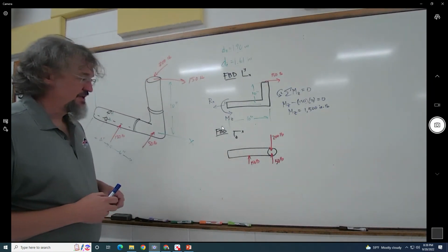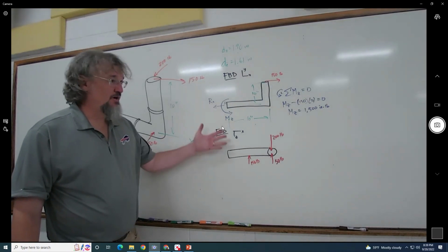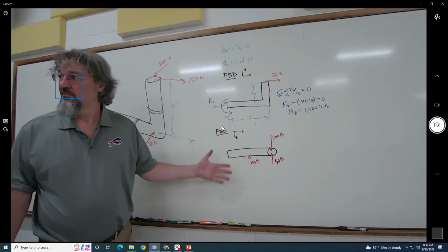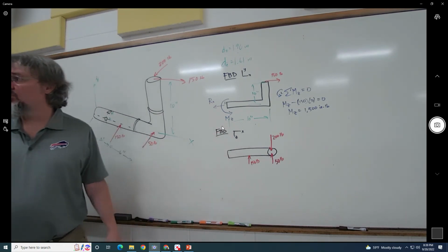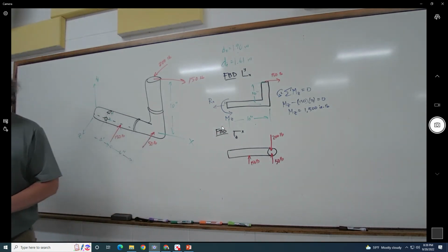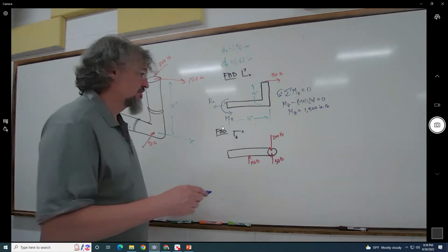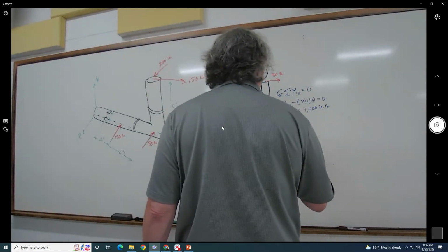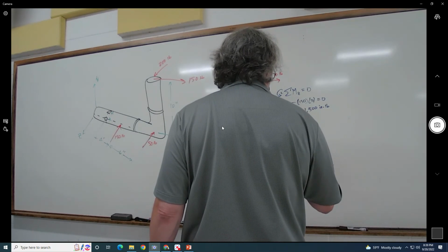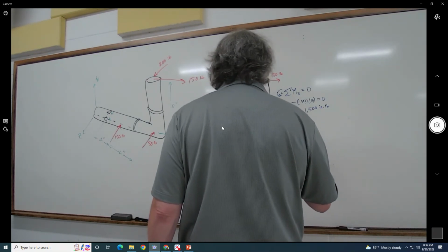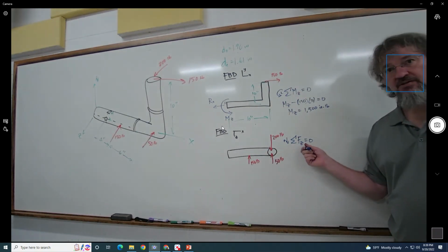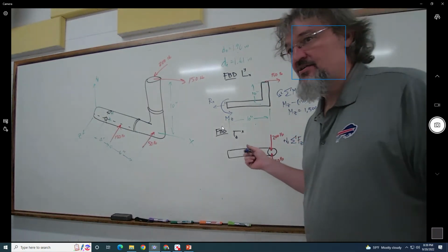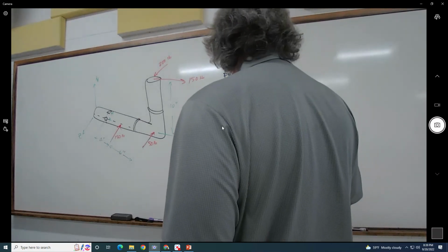So it's going to have no reaction in the Z direction force, but it might have a moment. So it's a little bit of a trick, right? You could test yourself with the sum of the forces in the Z direction equals 0. And when in doubt, if you're not sure, this is going to be your savior, and double checking the thing, because you don't want to be caught out cold.